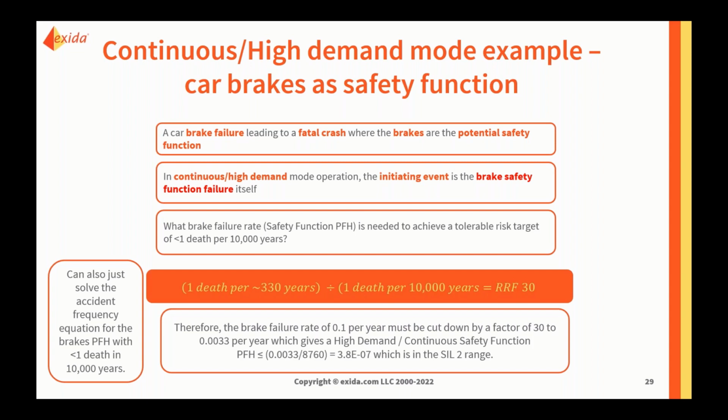So fine, either way works, and both of those approaches give us a requirement on that initiating event frequency to be 0.0033 per year, which, converting it into the language of SIL, PFH, probability of failure per hour, gives us 3.8 times 10 to the minus 7, which sits in the middle of the SIL2 range.